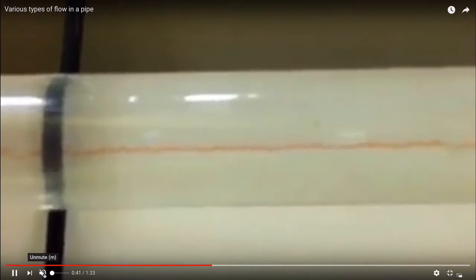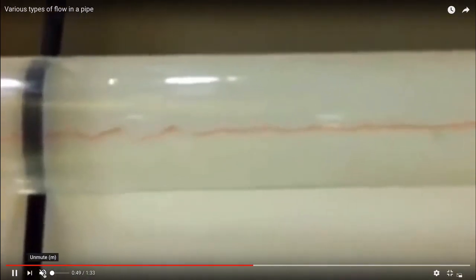And so as the fluid velocity is increased, Reynolds number increases proportional to fluid velocity, then the losses on the walls of the pipe, which occur to make the pressure at the downstream end different from the pressure driving it at the upstream end, we can calculate those. And so we can account for what kind of pump head we might need to be able to drive flow downstream. So that's essentially what we're attempting to do now.